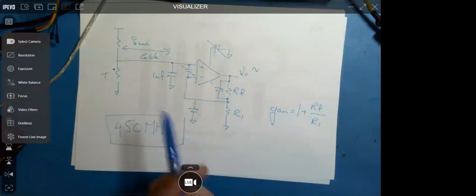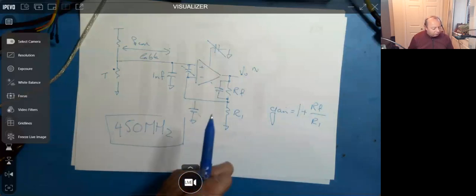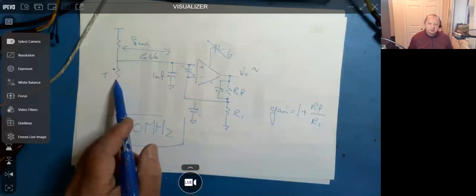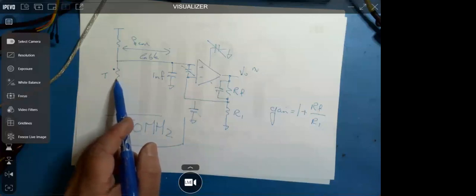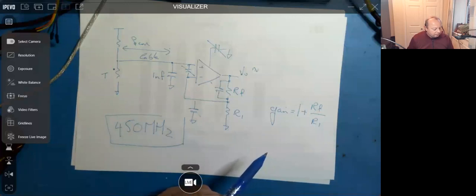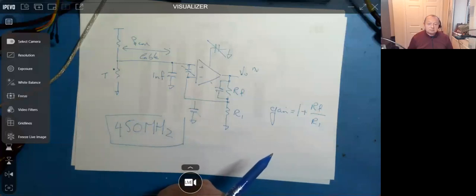I think that's asking for trouble. I'm not saying trouble at 450 megahertz. I think from a noise perspective, it's asking for trouble. If you're trying to measure small variances in temperature, these are also non-linear as well. So there's another issue. I think you just mentioned that, didn't you, William? The non-linearity. Well, it is really the non-linearity resulting from putting it in a potential divider. Yeah. Even in relation to temperature.